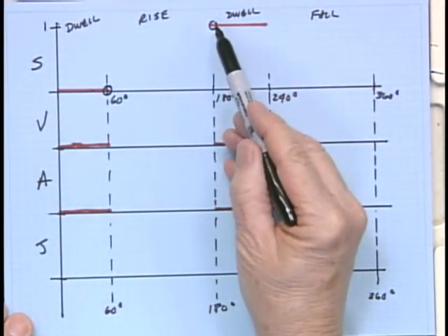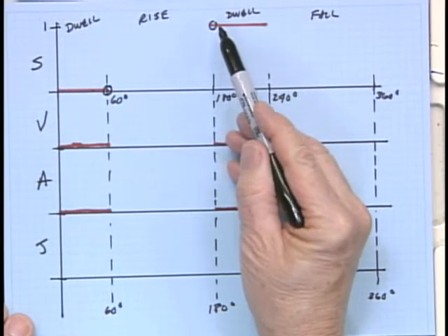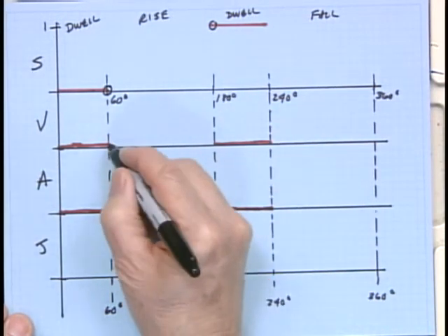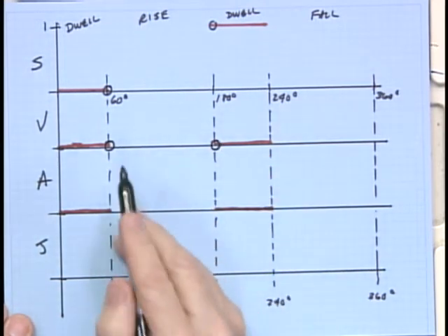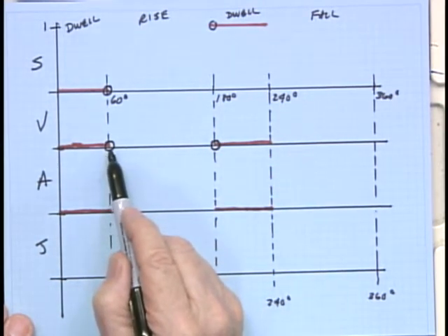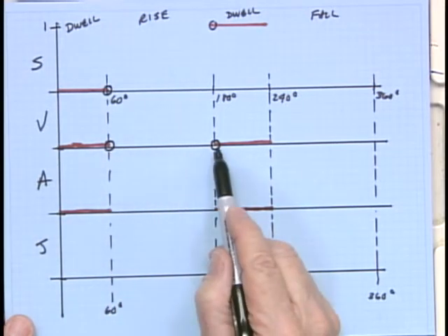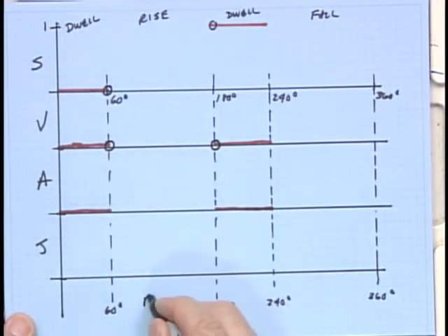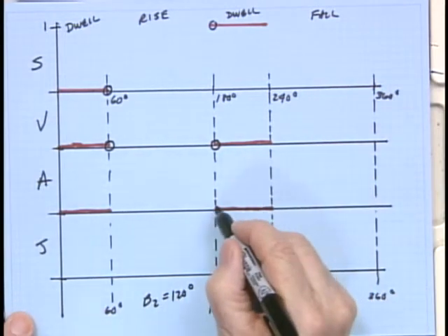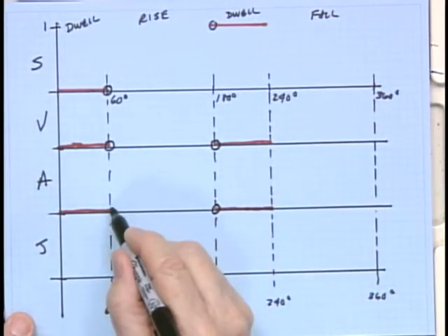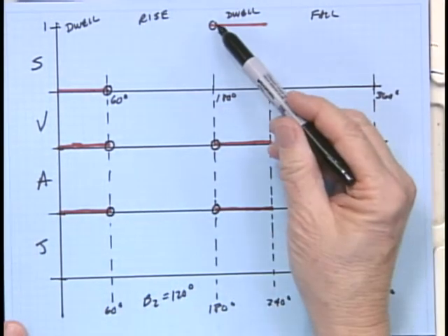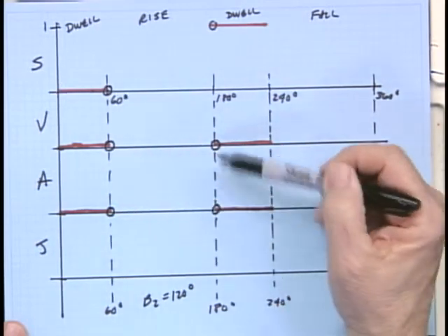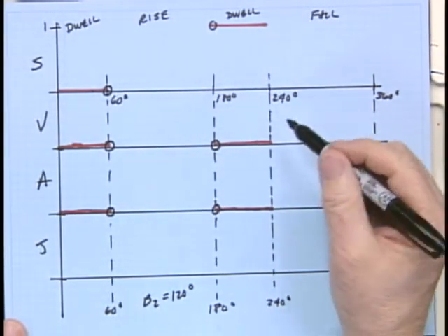So there are two boundary conditions that I must input to get my polynomial. The velocity must match as well. That gives me two more boundary conditions. 0 here. This would be 0 when beta is 0, and this would be 0 when beta is 120. Remember that the beta was 120 degrees for this particular segment. In like fashion, the acceleration has to be 0 at both. This gives me a set of 6 boundary conditions which can be expressed in little mathematical notation.